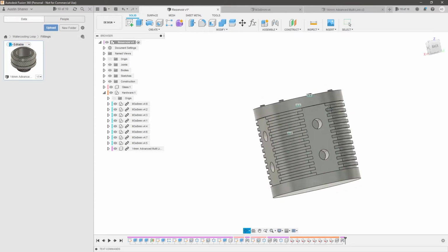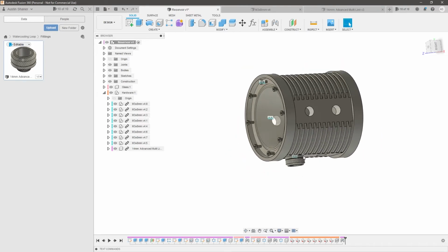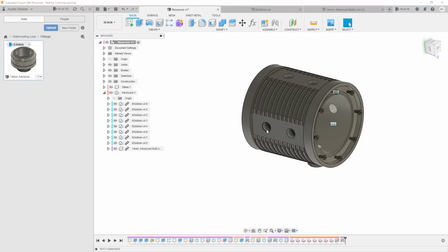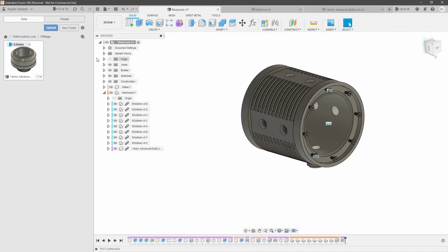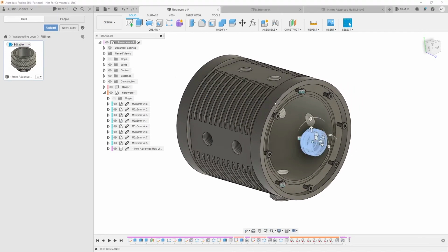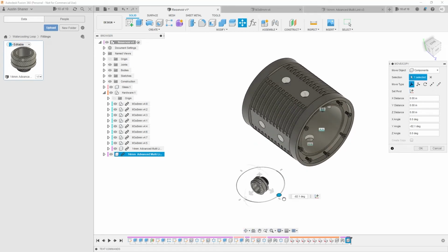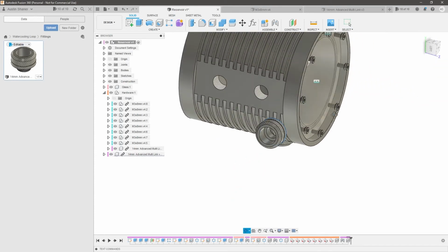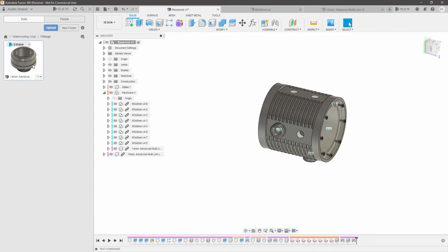So let's go ahead and say we want to have this one as an outlet that is feeding into the pump. And let's say we need to have that back one right here on the sides as an inlet where it's returning from the radiator. So I'm going to insert this and let's rotate it around. And let's join it. Here, J, enter. And let's bring another one in.